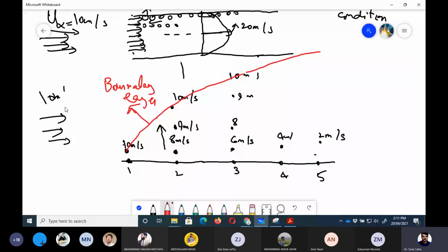So you can see that the boundary layer, we represent it with the symbol delta, and we would also discuss it again in chapter number 8. And delta is a function of x, and we can easily see that this boundary layer is growing in the x direction as the flow proceeds. But after some time, in this case for the pipe flow, the boundary layer can only grow up to the center line, like this.